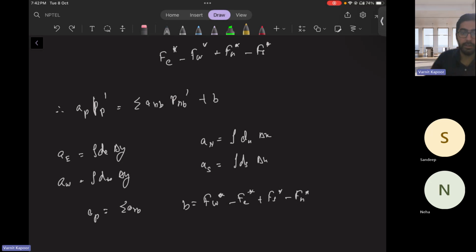And we see that this is the idea of the SIMPLE method, semi-implicit. You start off with the continuity equation, and by enforcing the guessed velocities to satisfy the continuity equation in terms of corrections, we have arrived at the equation of pressure. So the continuity equation is transformed into an equation of pressure correction with the help of the momentum equation.